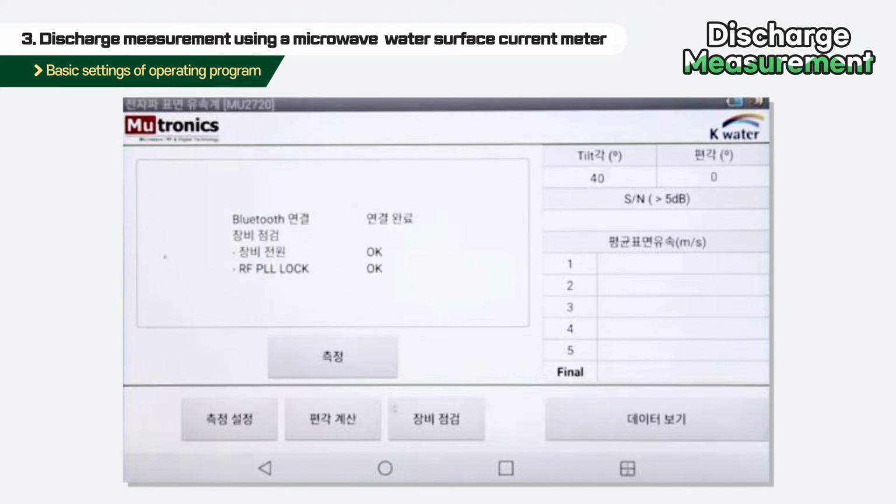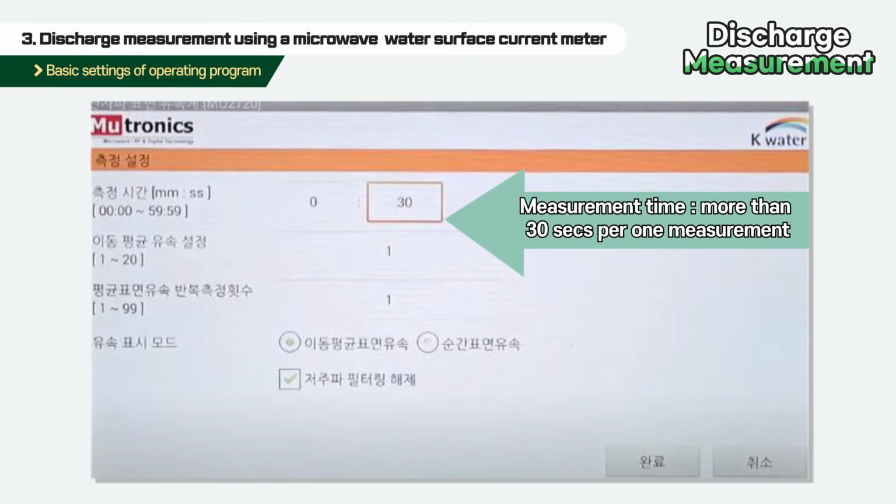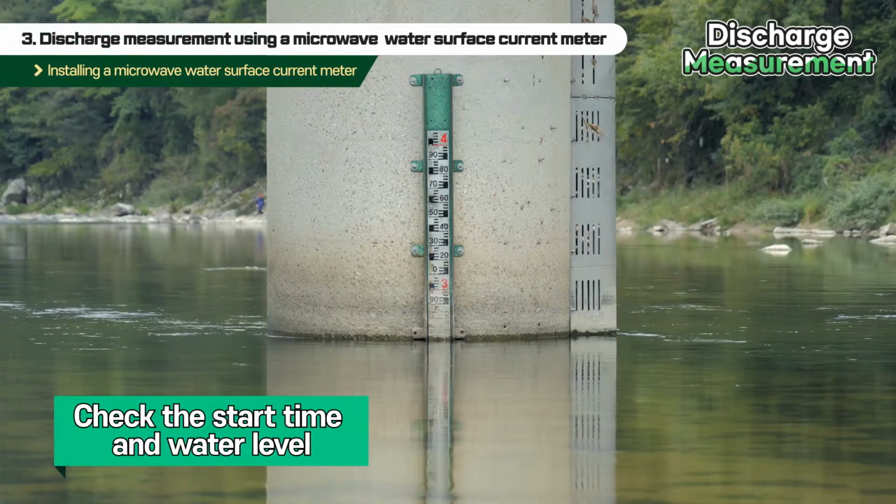If it is confirmed that the connection is normal, press the button of the measurement settings at the bottom. The on-site worker should set the measurement time, average current speed of movement, the number of repeated measurements of the average surface current speed, and the current speed display mode. Here, the measurement time is set to 30 seconds or more for one measurement to reduce uncertainty. When all inputs are entered for settings, please press the Completed button to end the setting. Additionally, please check and record the start time and the water level.